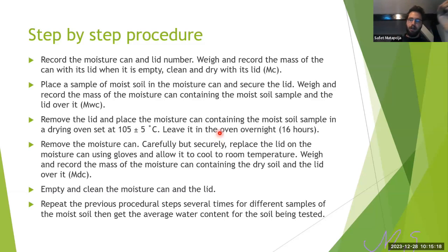So usually I used to do 3 times for the moisture content, and every time except the Atterberg limits, because they need 3 or 4 hours of pure work. So just do the 3 samples and you're going to be fine, and you're going to get an average result from it, and that's going to be everything you want. So let's go next.